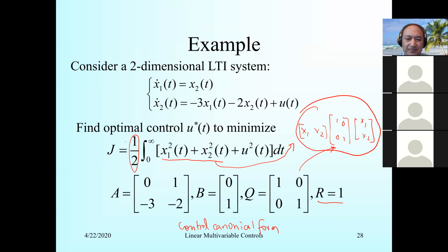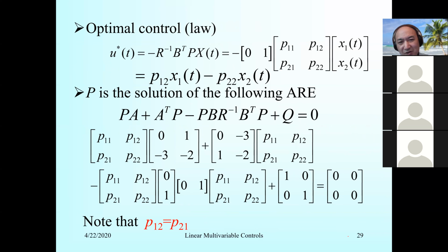So let's try to solve the infinite horizon LQR. In MATLAB, this can be done easily. It's called just lqr. You give it A, B, Q, R, and it gives you a K in the LQR sense. But let's do it manually to see. We'll try to find P. But P is symmetric, so this one and this one should be the same. When we do that, we only have actually 3 unknowns to care about. Be careful, we use this symmetry here, so this should be the same.